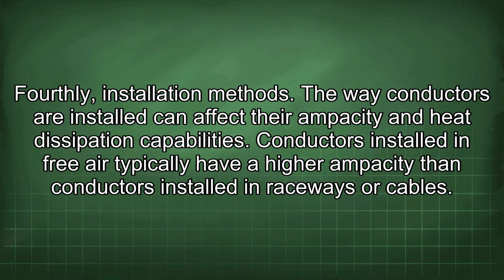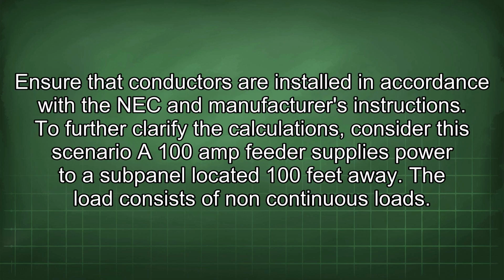Fourthly, installation methods. The way conductors are installed can affect their ampacity and heat dissipation capabilities. Conductors installed in free air typically have a higher ampacity than conductors installed in raceways or cables. Ensure that conductors are installed in accordance with the NEC and manufacturer's instructions.